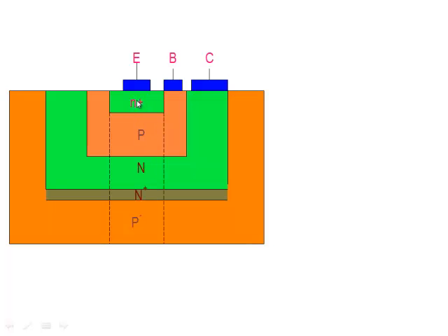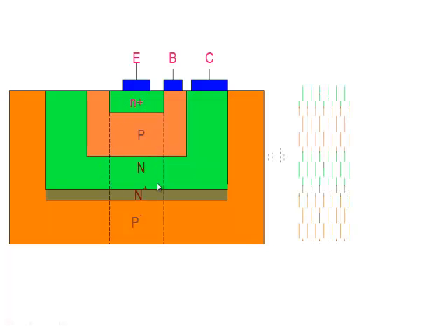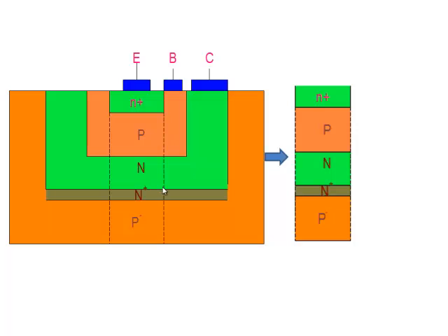This is the place where electrons are injected. They go to the base here, they recombine with the holes here, and then they come here. So this is the heart of the transistor. The other things are like support structures. To provide a contact here, I need this region here. To provide a contact at the top, I need this region here. The real transistor is over here, the portion which is shown between the dotted lines here. That's the real transistor. The rest of it are simply spaces to provide contact. Okay, so that's the transistor here.